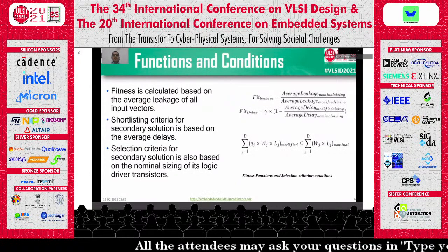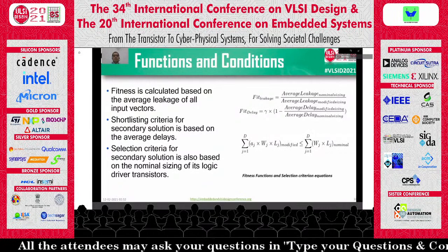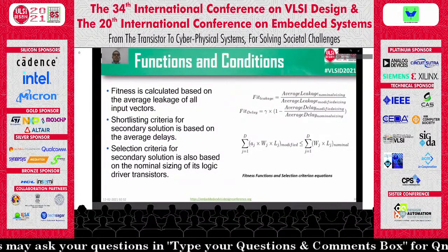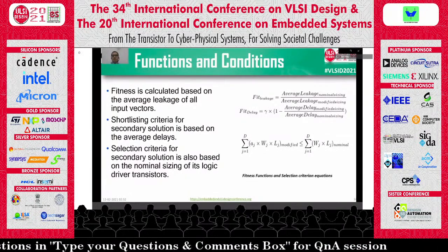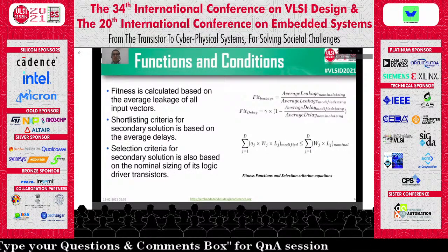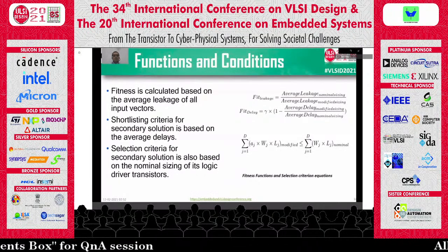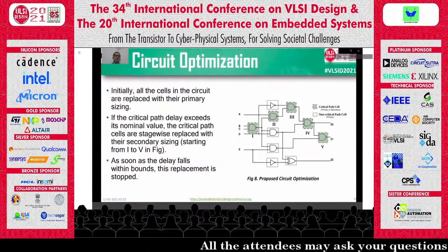So based on the values generated by these fitness functions, the quality of a solution is adjusted based on the values generated by these equations. The inequality condition mentioned below is generally used so as to keep the sizings of the logic driver transistors of a cell within bounds, and hence it helps to control the input capacitance of the cell.